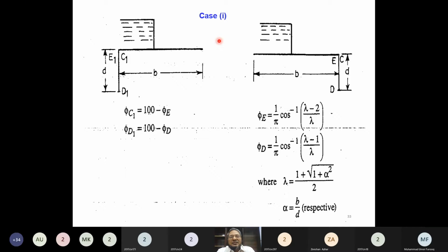And if this process continuously takes place for a longer time, and if it is not checked, and if we don't do its solution, then what happens? You know, the porosity of the soil under the hydraulic structure keeps on reducing or increasing. The porosity will increase. It will become more porous. And when the porosity increases, due to the load of the structure, there will be collapse of the soil and ultimately the collapse of the hydraulic structure, particularly due to undermining.